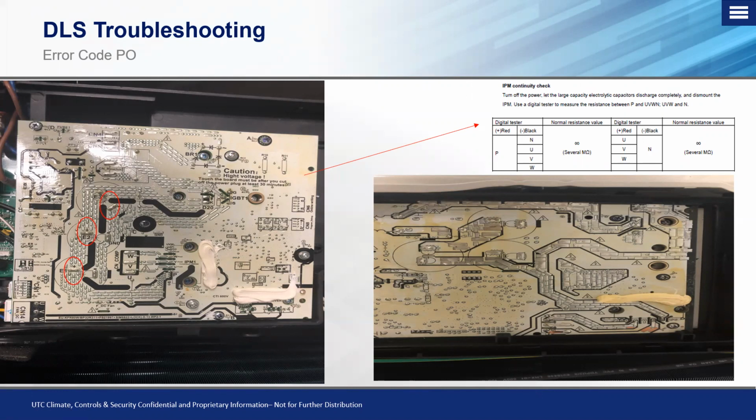So if you're trying to troubleshoot a board, or troubleshoot if something is getting funky inside of this board, you can always take your meter, set it for AC voltage, and go between these two terminals. And you're looking for line AC voltage. Now, if you follow this down through here, you'll see this little diagram right here. That is our bridge rectifier. That's where we take this incoming AC voltage and rectify it over into DC voltage. Okay, so that's where that's happening right there.